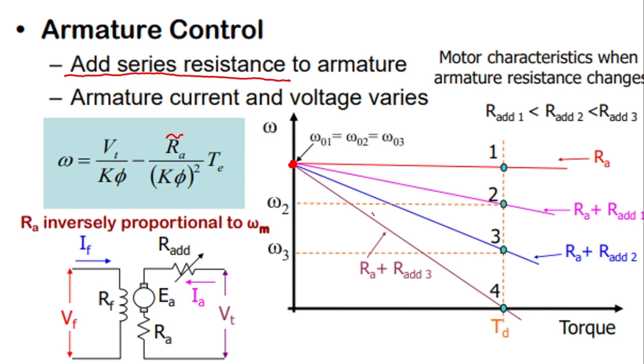But you notice as the line gets steeper, for the same torque, the speed is actually dropping instead of increasing. Yeah, because the value of the gradient is getting bigger, but it's getting bigger on the negative side. It's not getting bigger on the positive side. So it's not going like this. It's actually getting steeper, but it's steeper going down.